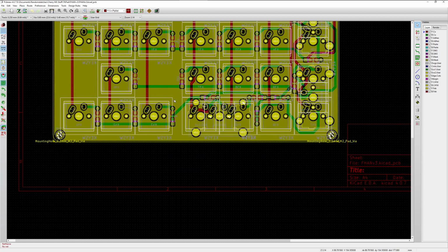Okay, so let's just check them all out to see what the issues are. And it seems like they might all be related to the mounting holes that we used. So, yep, that's a mounting hole issue. That's a mounting hole issue. Mounting hole issue. So it reads like all of these. Oh, okay. So what's this one? This is an actual switch related one, is it? I'm going to turn that off again. So let's just see, because you can see all of these, the reference is all related to the mounting holes. And then there's 1, 2, 3 related to actual key switches.